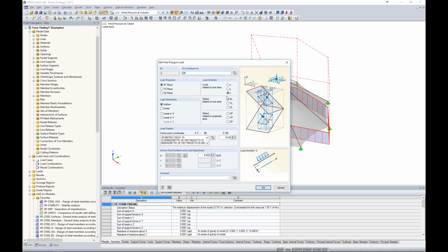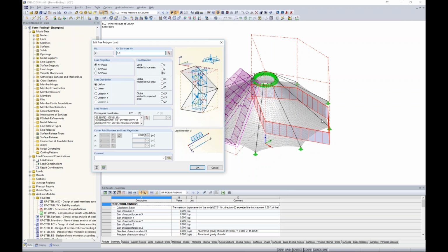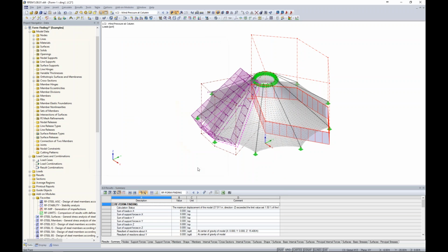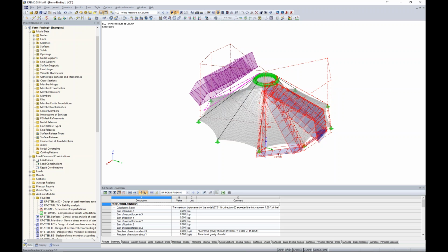Looks like I applied this to surfaces all. It's the same thing. You can leave it as all or type in surfaces 1 through 9, but you can see the display is a little bit different. Just goes back to it's being projected. We can project down through multi-level story buildings as well. But just for display purposes, I'm going to select this as all just so that it's very clear this is a suction pressure at the rear of our structure.